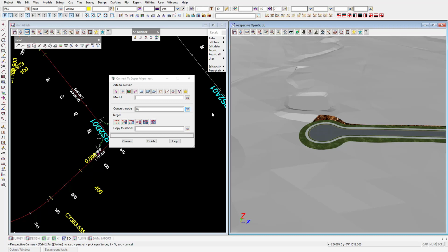Yeah, so normally I just trace them off, and you get the added benefit then of being able to change them really easily, and then if you do need to take them back into CAD, take them from 12D back into CAD. Just do a write out to a DWG file and write them out to 2D, and then the horizontal geometry will get out.